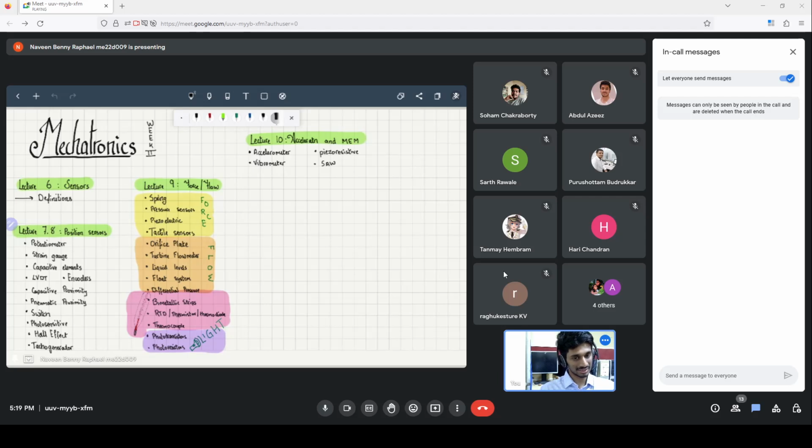The essence of capacitive position sensors is that we have a capacitor, and we know that the capacitance of this capacitor depends on the dielectric medium inside. Therefore, by changing the dielectric medium we can change the capacitance, and this essentially gives us a measurable input.